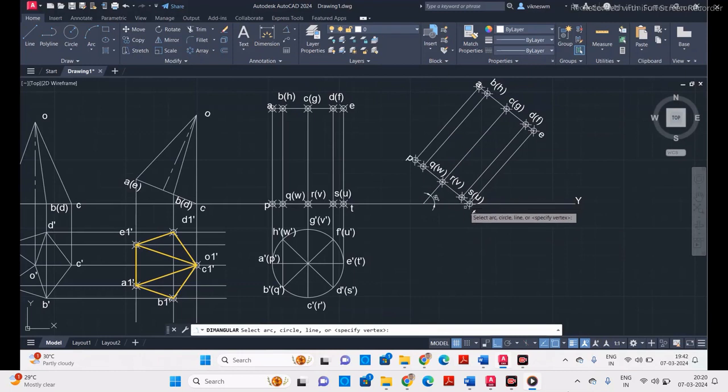And this one is 40 degree, which I rotated this rectangle about T. I took 40 degree by assuming that it is a right angled triangle. The sum of internal angles of a triangle is 180 degree. That corner is making 90 degree and we want this one to be 50 degree. If you add 90 plus 50, it is 140. 180 minus 140 is 40. So I rotated this about T by 40 degree, and this axis will automatically make 50 degree with this reference line.